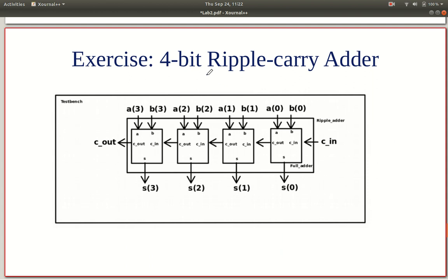So this is the architecture of a 4-bit ripple carry adder. So first you, for example, 1011 plus 1010, want to add these. So first you add the leftmost bits, right? So you add the bits A0, B0 at the index, you produce sum 0, and you produce a carry 0, which becomes an input carry to these 3 bits, and so on.